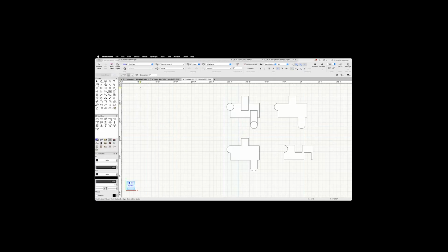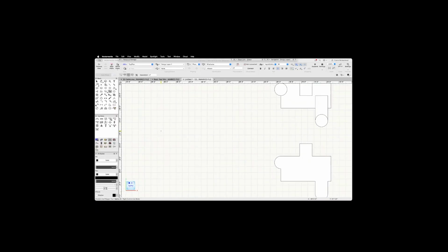But much like the double line tool, it has different modes that are referencing which line it is you're going to be drawing, and then what your overall separation is. So for now, I'm going to have it on right control line mode and have the separation be 6 inches. And I'm just going to click in some empty space on my drawing and drag my mouse off to the right. And basically I'm going to make a 4-foot double line square here.